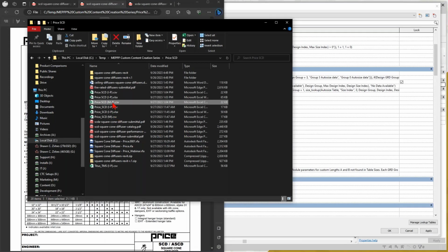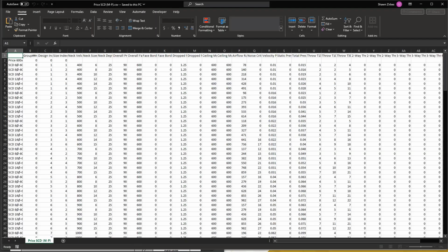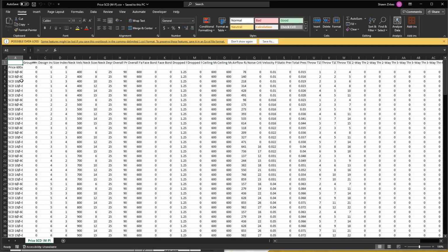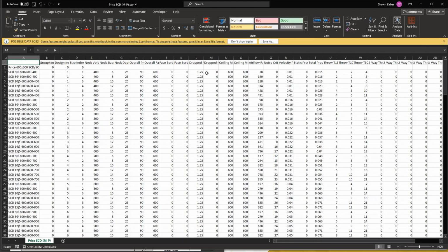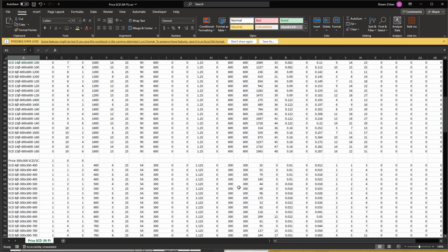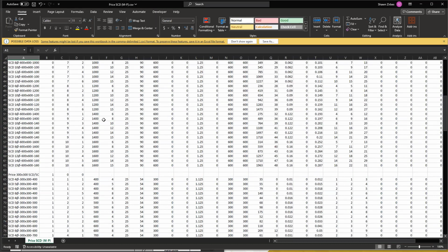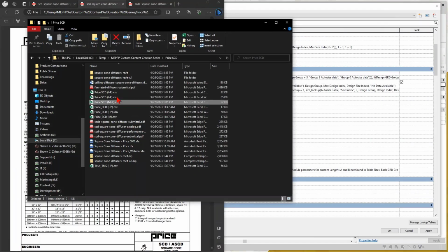I'm going to check the MP file, same thing. It should be the metric version. Yep, 600 by 600, 600 values. This is great. I've got all the metric properties in here that I need now. Save this guy, close it out. I'm done. These are ready to be brought right into the family, and I'm almost 100% done with all of my edits.